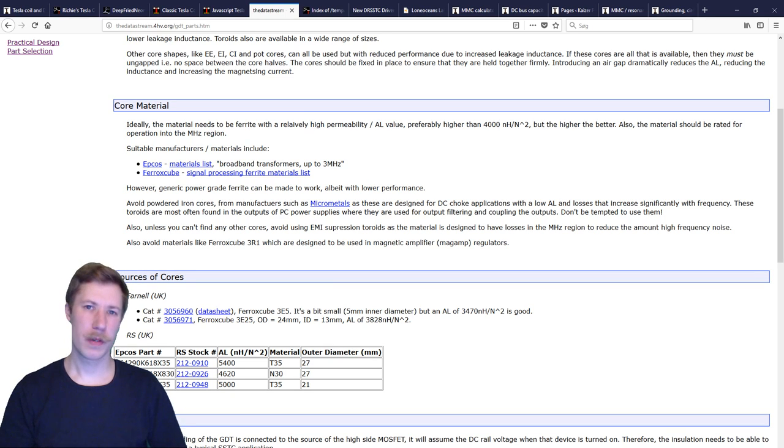Was it supposed to be to counter the frequency change because of arc loading? Because then even there it is getting way too complex to control, because changing two toroids apart from each other and changing the capacitance here, it will never be able to react fast enough and to regulate the capacitance fast enough to make up for the changes in arc loading.